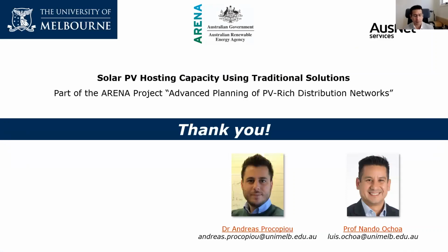Well, finally, also remember, as much as everything that has been shown today is very promising, because of the new Victorian PV inverter settings, we need to be very, very mindful that all our simulations consider that these settings were enabled from the very first installation of a house with photovoltaics. In reality, that is not going to be the case. In reality, we'll have a mix, a penetration of, I don't know, 10 or 20% already with the old settings, and the new settings will go on top of that for the new installations. That will mean that we will actually have different values of hosting capacity and different impacts on customers.